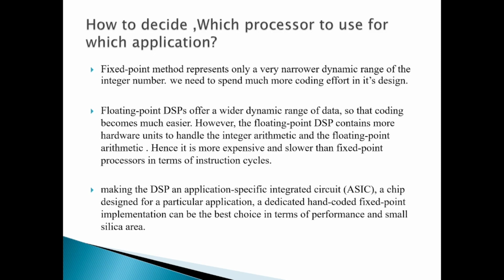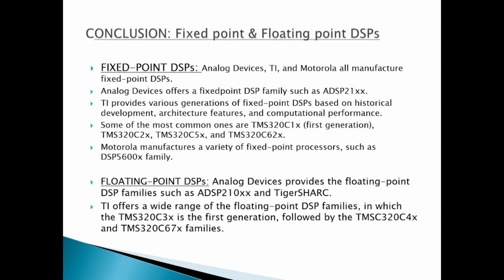For making the DSP an ASIC, a chip designed for a particular application, a dedicated hand-coded fixed point implementation can be the best choice in terms of performance and small silicon area. Coming to fixed point DSPs, companies like Analog Devices, Texas Instruments, and Motorola manufacture fixed point DSPs.